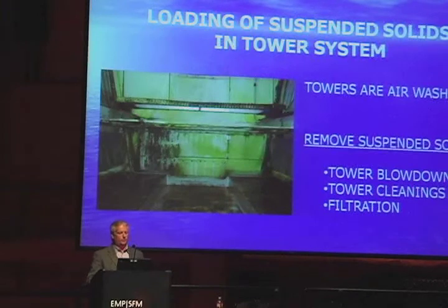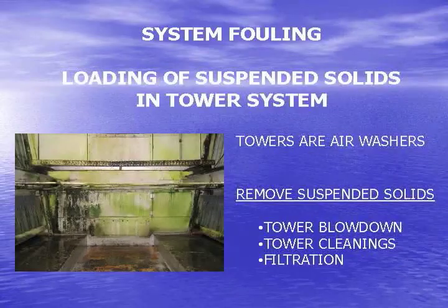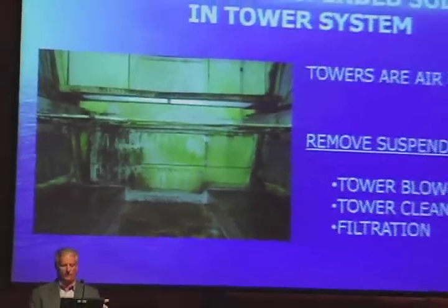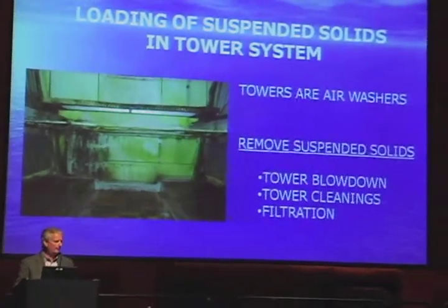Okay, and the last quadrant we talked about is fouling. Basically, like I said earlier, if you stand next to a cooling tower, your cooling tower acts as a big air washer. So if you're next to a road or next to a construction site or next to a high dust area like in Phoenix or Vegas, there's a lot of suspended solids that comes into the cooling tower because it actually cleans the air. That's one of the advantages of it. Unfortunately, the dirt particles go through your system, so it has a chance to be captured on the pipe surface or the heat exchangers, and it also settles in your tower basin.